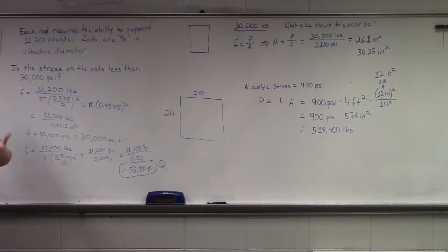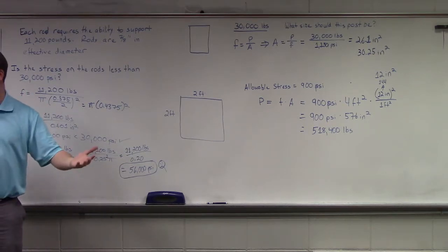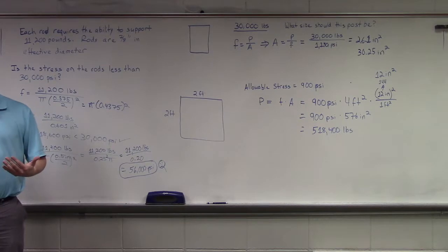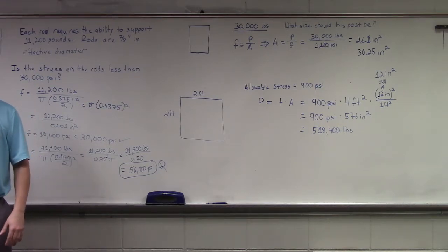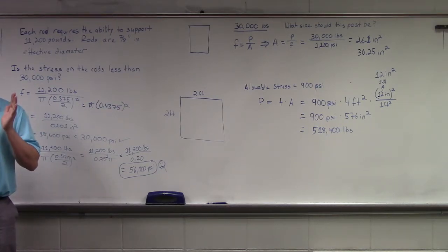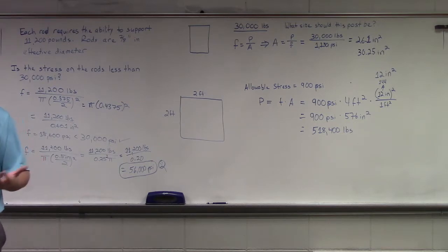How the actual world works is, as Marshall brings up, how do you deal with live loads? How do you deal with the fact that in a theater, sometimes you'll have 10 people go to a movie, but sometimes you'll have 100 people go to a movie? You'll design for 100 people all the time, saying that that's the maximum occupancy. And then as long as you can safely operate at maximum capacity, everything else is just less economy for the owner, such as it is. Okay.